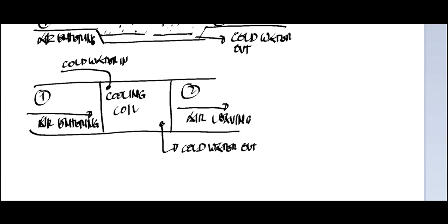So in the psychrometric chart, this is represented. So I'm going to draw that one in the psychrometric chart. So we're starting here, humidity 1, okay, and with the corresponding dry bulb 1. Then we're trying to dehumidify. So okay, here you have your point 2.